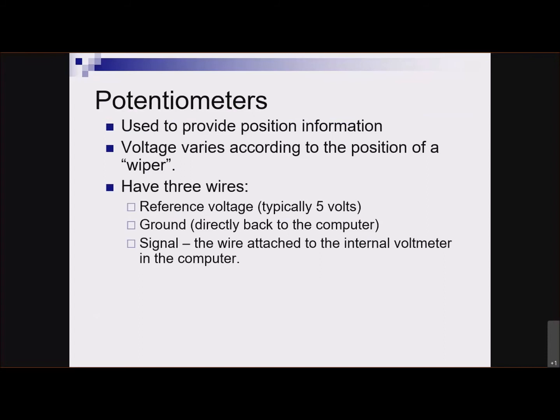You know that your battery voltage is changing all the time, right? If you have a voltmeter on your battery and it's reading 12.5 volts with the engine off, when you start the vehicle, it's probably reading more like 14.5. If you turn on the headlights and the rear defroster and the blower motor on high, and then the engine cooling fan kicks on, that 14.5 volts might drop down more like 13 volts.